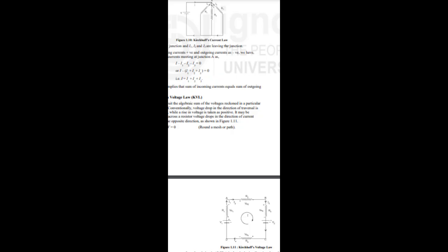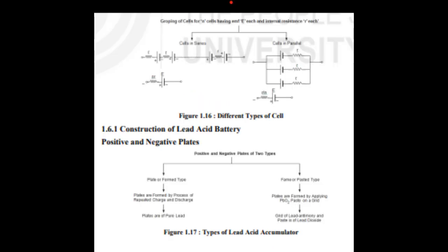1.4.1 Resistance of resistors in series. Resistors are said to be in series when they are connected in such a way that there is only one path through which current can flow, figure 1.4. This means current in a series circuit is the same in all parts of the circuit. The voltage drop across each component in a series circuit depends on the current level and the component resistance.